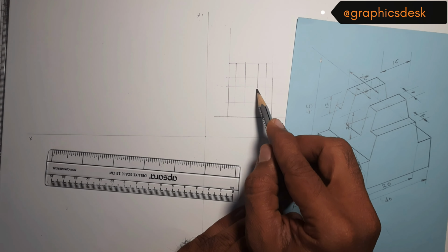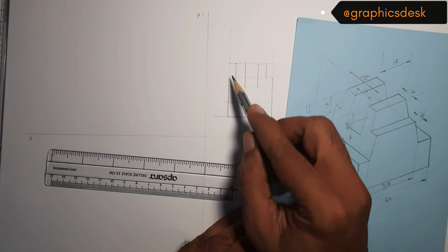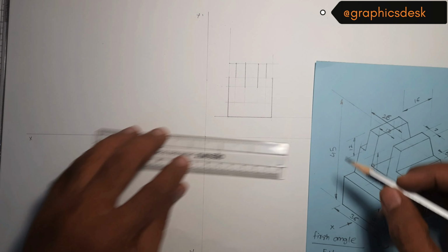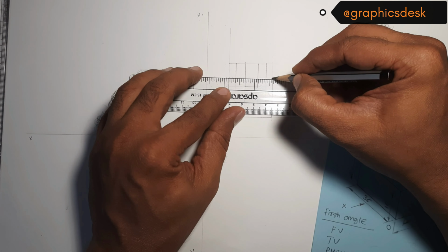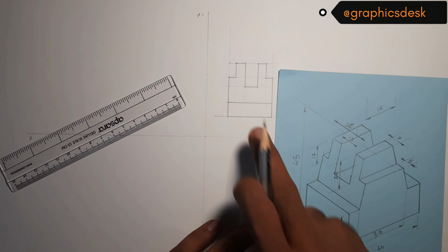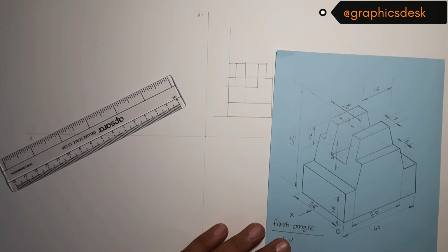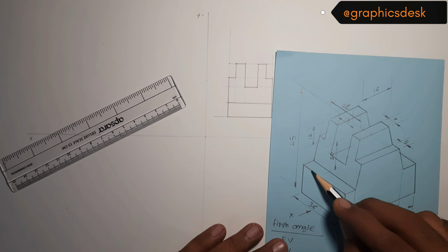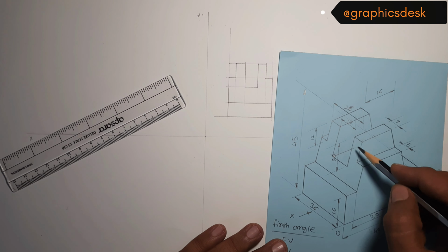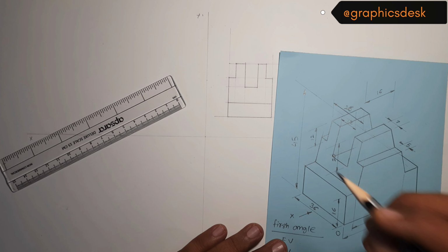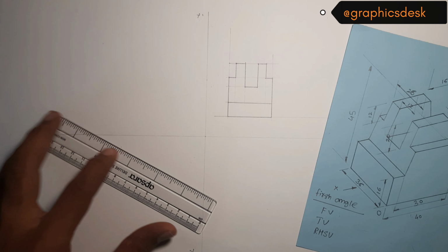This line will be connecting these 2 points, and then we'll have these 2 points connected. And again, at the top, we have the solid line over here. Now, this is what our front view would look like. We don't have any dotted line in this because the only possible dotted line is this one, which is essentially superimposing this particular solid line, as the line opposite to this, this and this, but these are superimposed, so we don't have to draw these lines. So this is how your front view will look.